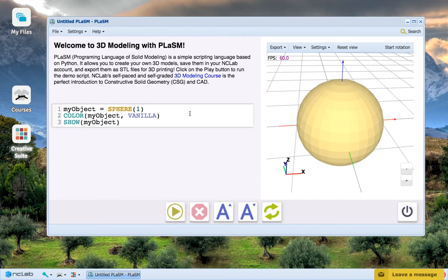By using a second parameter in the sphere command here, you can control the number of each of these types of lines that are used to create the surface, which will control the number of faces used to approximate its smooth surface, and the overall computational cost of the object. The second parameter is a list with two items, which works like the extra parameter in the elbow command does.